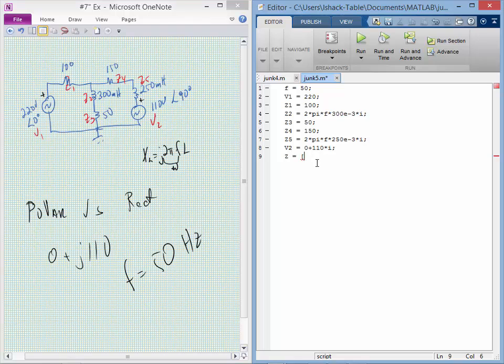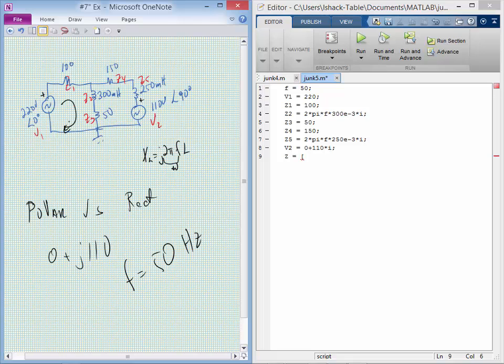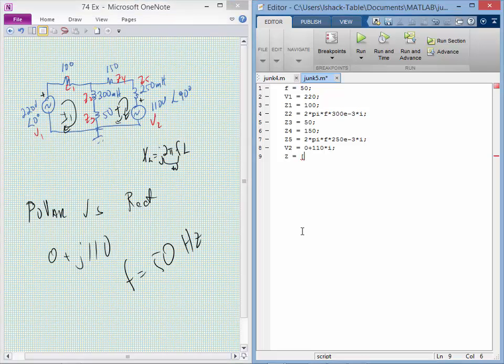So Z1 has got 3 impedances in it, right? Again, we're following the same rules. I didn't draw the loops here, but I always draw the loops inside and clockwise. So if I draw them inside and clockwise, this is I1, this is I2, and it goes in this direction. As we look at loop 1, we've got 3 impedances, Z1 plus Z2 plus Z3.